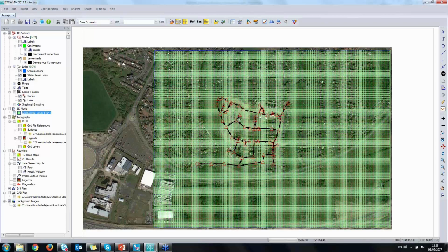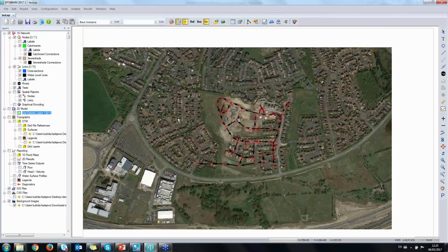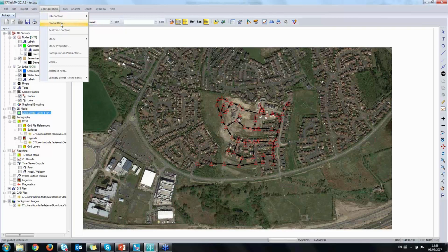After having the grid in there, I want to use the most dangerous rainfall, right? The one which is the critical one. Peter identifies that this will be the 1 in 100, 15 minute winter profile. When we import the MicroDrainage file, it imports our design criteria rainfall, the one we used for sizing pipes. So all I will do is quickly recreate the rainfall.